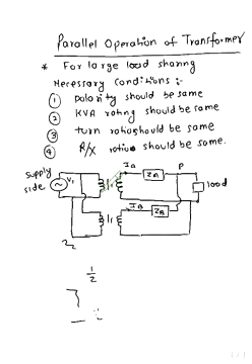So here we can see the two transformers A and B, whose primary windings are both connected to the common supply side, and there are two currents IA and IB, which together make the load current IL. This is the impedance of transformer A, this is the impedance of transformer B, and both secondary windings are connected to the common load side, and that load voltage is VL.